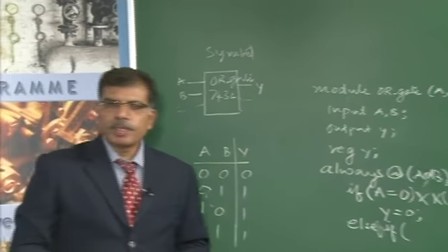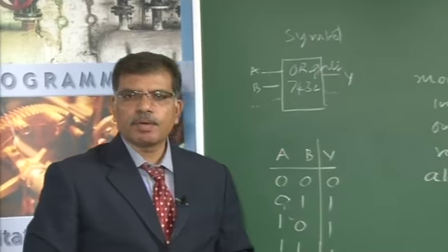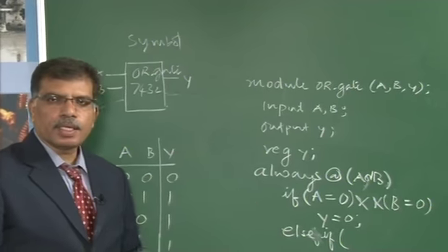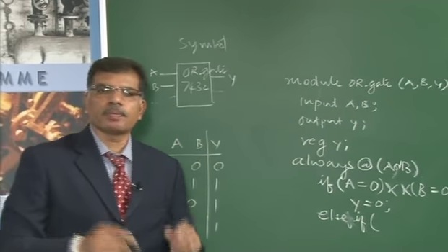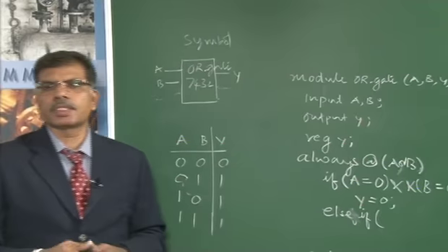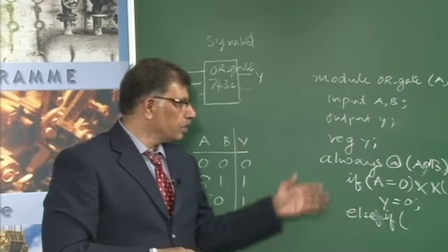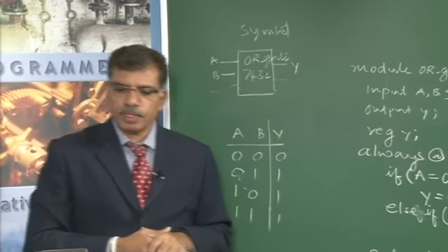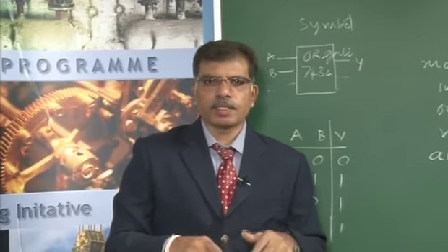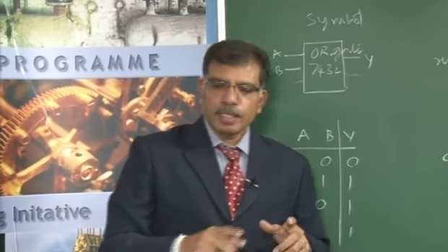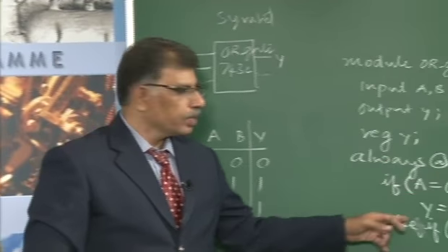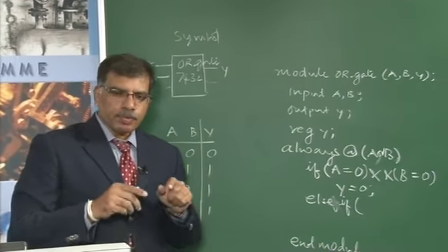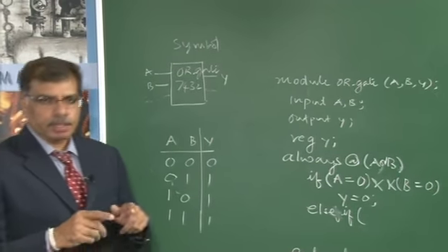Okay, so now we will see, after writing this in software, we check the syntaxes, whether the syntaxes that I have written are correct or not. If the syntaxes are not correct, naturally you cannot simulate it because it shows syntactical errors. Then you have to check the syntax and correct it. Then you go for simulation, either by using a simulation tool directly which supports waveform entry, by forcing values to inputs and seeing the output in terms of a waveform. Otherwise, rather than forcing the values directly by using a wizard or a waveform,